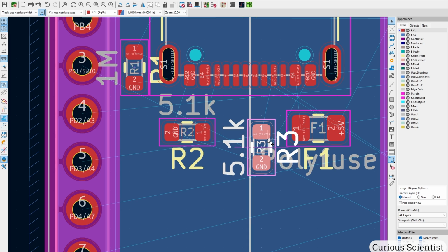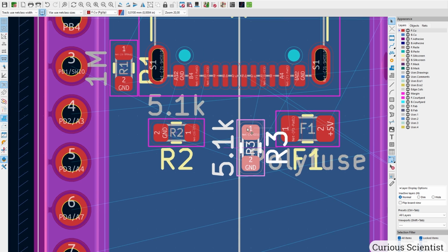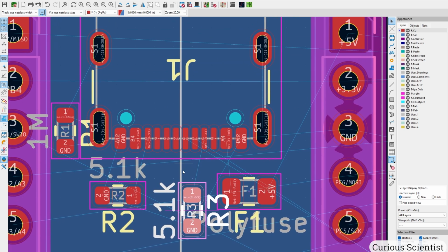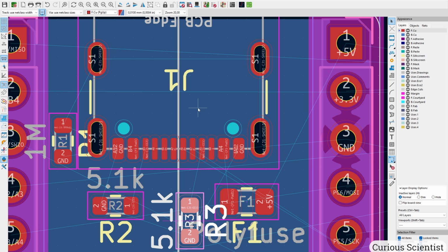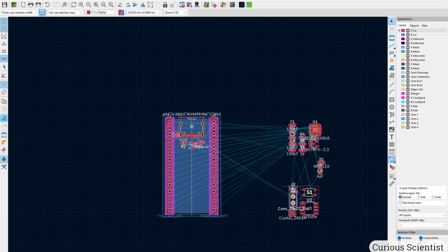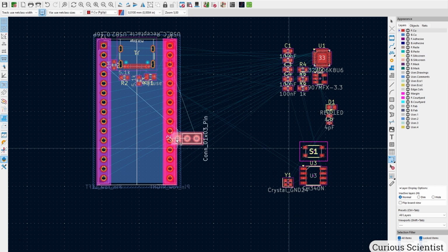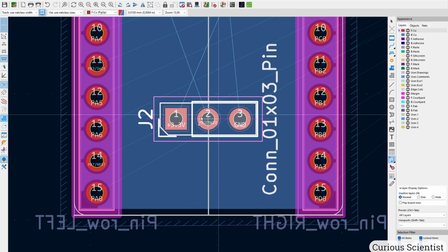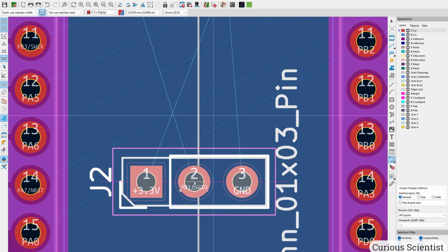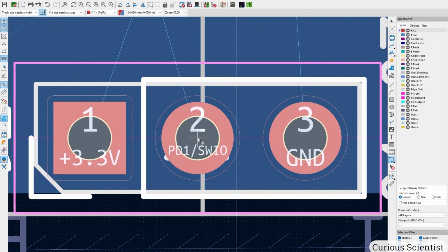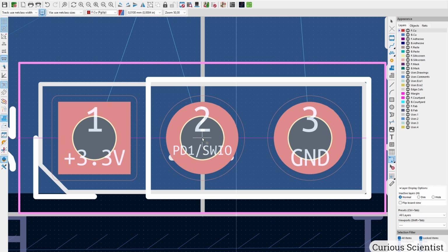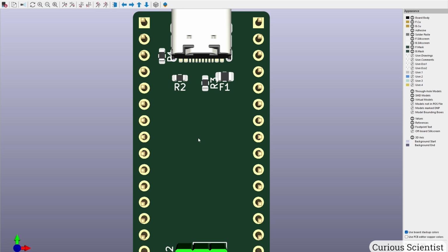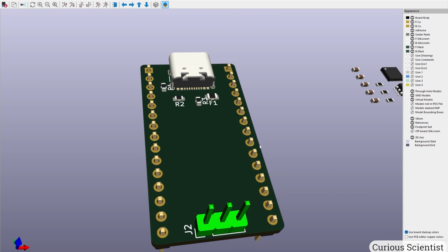I don't align anything perfectly here yet, I just put them roughly at their, let's say, desired places, but then I will clean up the board once I start laying out the traces. The J2 connector, which is the programming connector, can be placed actually at the end of the board because that's relatively easy. So I grab the hole number 2, and then I bring it all the way down to the center and at the end of the board. So something like this. If I check, then it's sitting there. That's good enough.